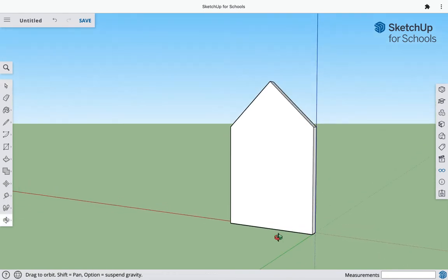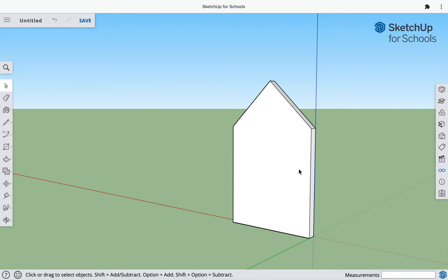We're making a birdhouse. Next thing we got to do is make some walls. Okay. So let's go ahead and select our rectangle tool again, or you can press R on the keyboard. And we're going to decide where to start our wall from. Well, I want to start in this bottom corner over here. I'm going to make the height and the thickness of my piece this time, and then we'll extrude it a certain width, okay? So I'm going to do a single click down here. I'm going to move in the correct direction, so about here, right?